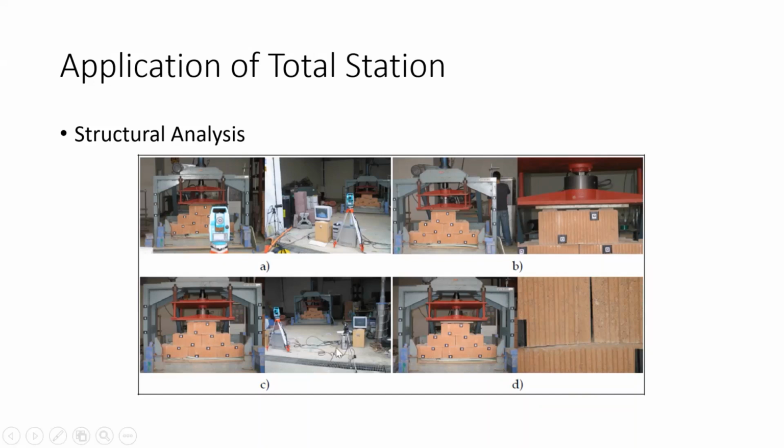And also you can see there is a camera here. The amount of displacement is measured on the screen, and also using total station we have matched it. So there are two things here: photogrammetry, this is close-range photogrammetry. There is a camera here. Can you see the tripod here? There is a tripod. This will be taking photographs or a video continuously, and also the coordinates are measured before the load and after the load, after the failure. So this is a combination of totalization and photogrammetry.